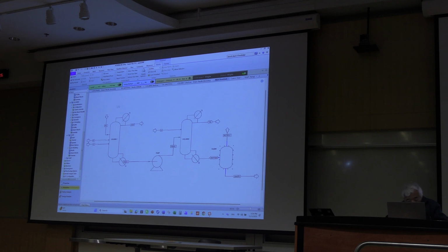Now, you should not close the recycle loop until you are happy with the number of stages, xylene input mass flow rate, and feed tray location. You get an ACN 0.9987 with some safety margin. The same thing happens to column 2. You're happy with the number of stages, feed tray location, reflux ratio.